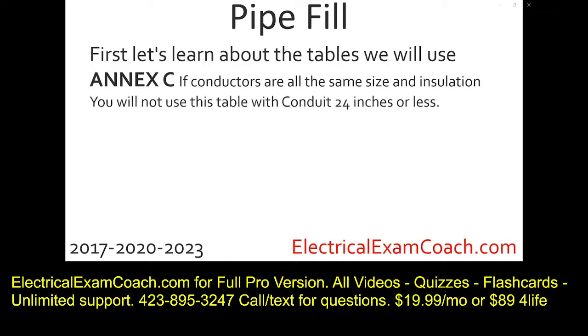You will not use this table if the conduit is 24 inches or less. Now, the code book uses the term nipples, but I want you to imagine in your mind, anytime the conduit is 24 inches or less, you're not going to use Annex C. You're going to use the method that I'll teach you in Lesson 7.2.